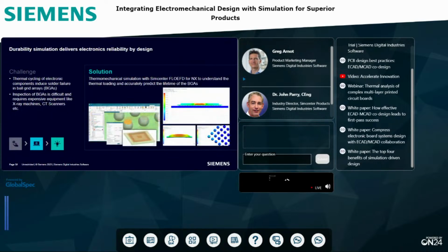One of the leading causes of failure in electronics assemblies is low cycle fatigue. That occurs typically in the package interconnect, and that's solder balls in packages that have a ball grid array underneath, or BGAs for short. The recent development in 2.5D and 3D, high density advanced packaging and advanced solders has led to really a renewed focus in this area.